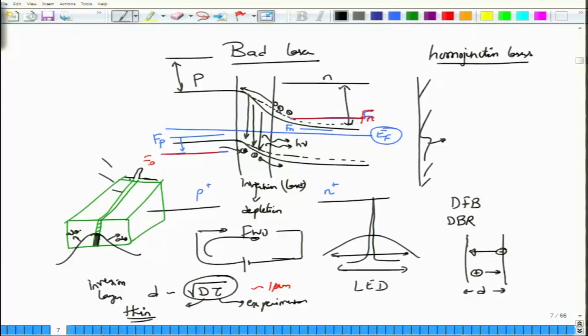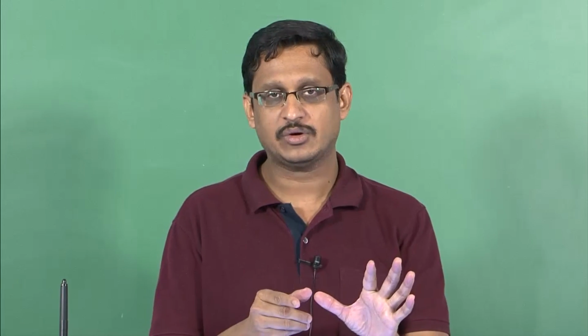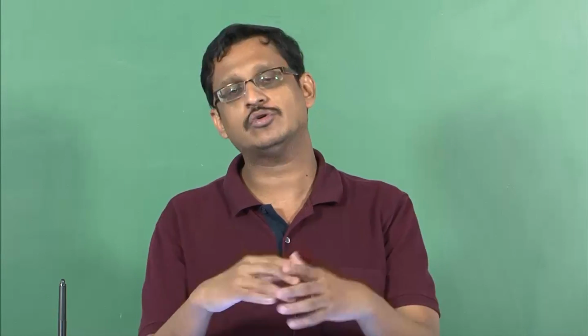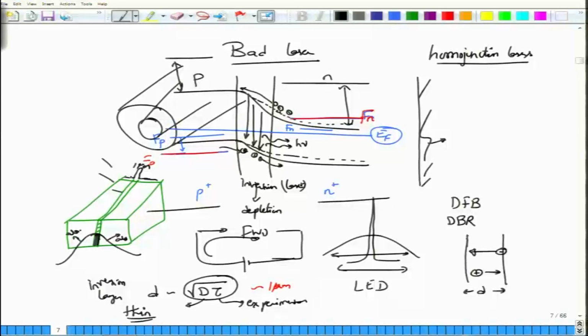And what is the problem with this? When light comes out of such a small aperture, which is about 1 micrometer, and let us say you have a fiber whose cross section is about 4 microns or about 50 microns, then what you have is a pinhole kind of output which is subjected to heavy diffraction. As soon as the light comes out, it will spread out and be expanded, and therefore loses all or most of its coherence properties. So, it would come out spread in this region and therefore it will not be a good laser.